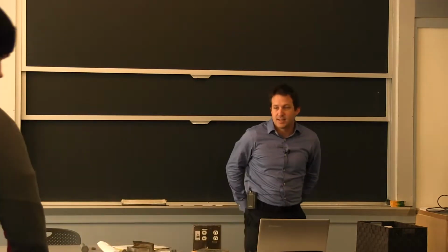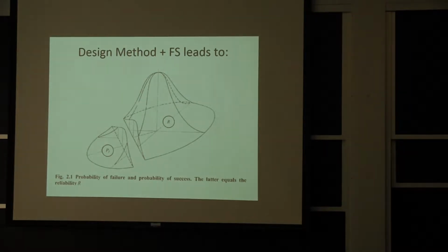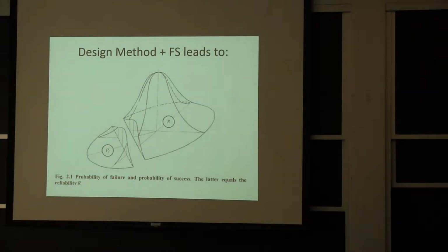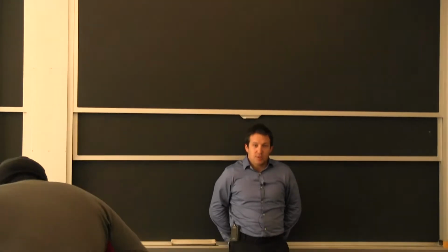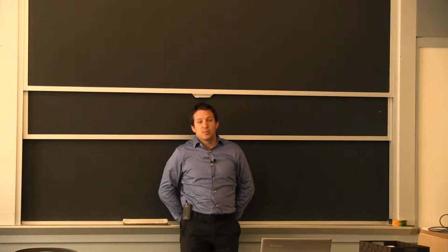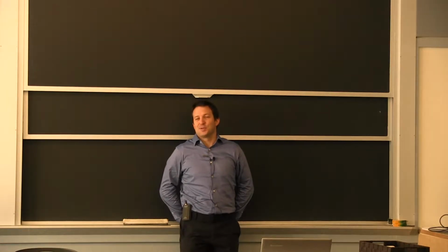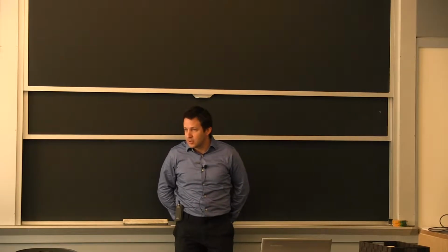Obviously, failure analysis is slightly different from one industry to another, but the base principles are the same. If something goes wrong and you're one of the first ones to be called to find out what happened, you have to be careful with what you do. You can't just take the broken piece and melt it to figure out the melting point. You have to think that there will be other people also interested to learn from it.